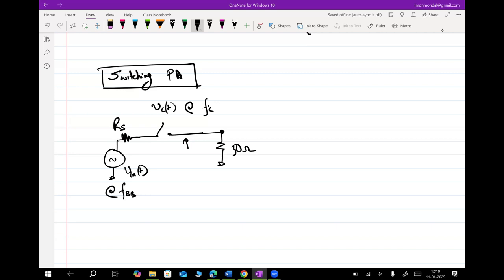So the load that we typically design for in analog circuit classes and amplifier drives is either a capacitive load or some resistive load of kilo ohms, maybe 10 kilo ohms or 1 kilo ohm or something like that, right? So that is a typical range of loads that our amplifiers can drive efficiently without losing bias or having very poor efficiency, right?